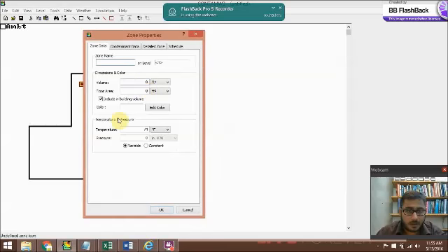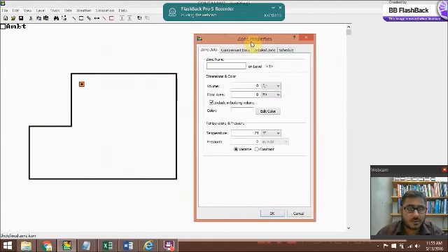Even though you have mentioned your cells, it would not automatically calculate your area. Your floor area would have to be entered into this. So maybe we say right now it's around 400, and based on your height, your volume would automatically calculate. So you can understand what your height is.